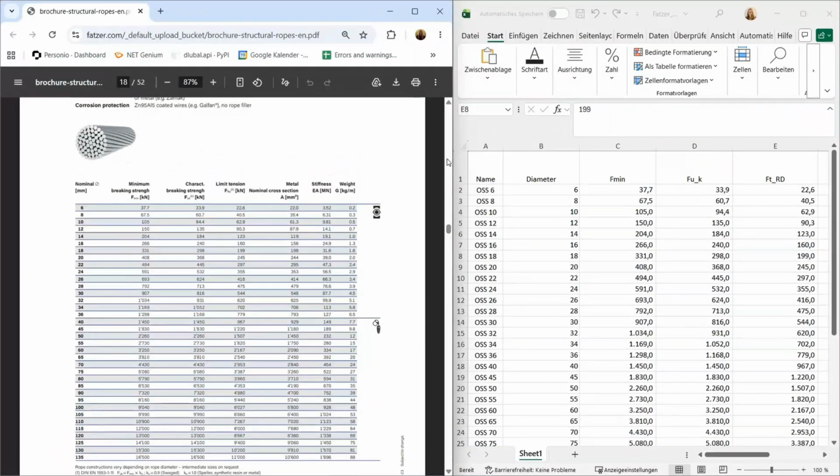And what's important is that every line of the file has a specific name in order for RFEM to know which components are included in one series, and the name of the columns is also important for the JSON file, which I will show you later.